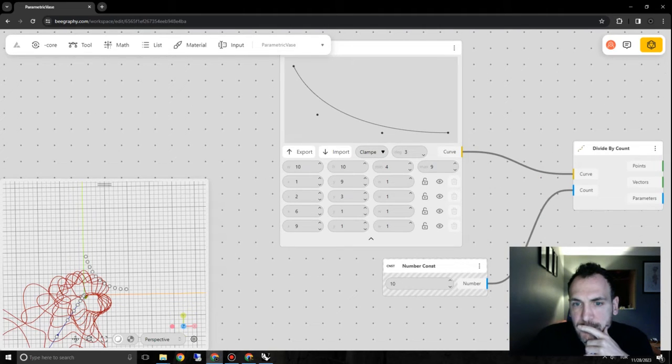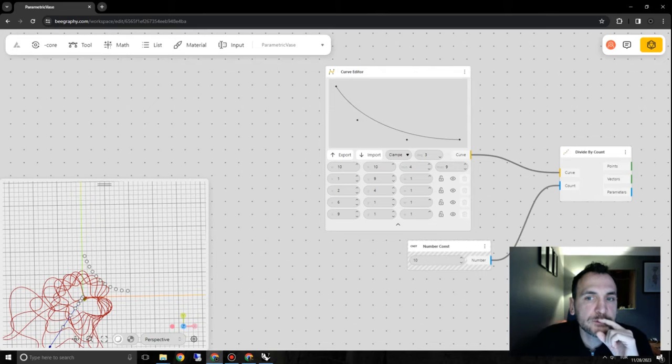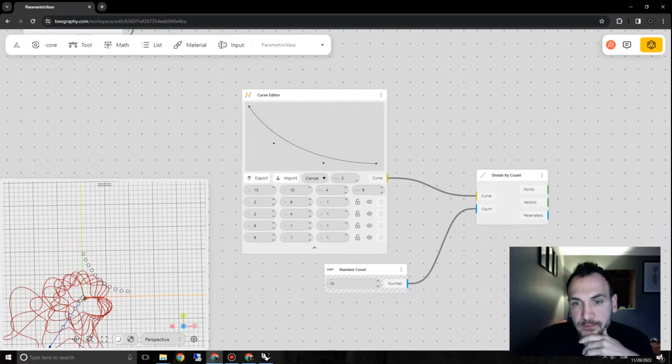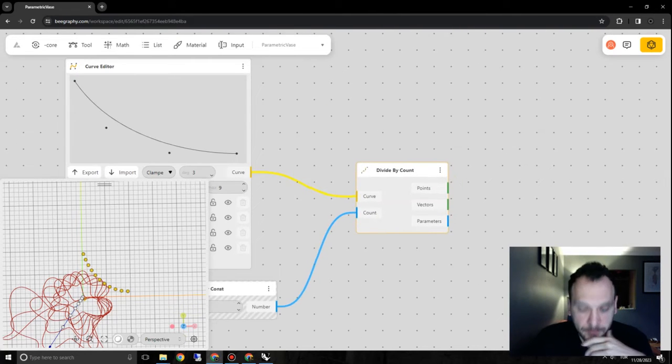Well, we can actually make it, this is, I guess, the number of points. Well, I'm not too comfortable with playing with these because I want to manually change the shape of this curve. But what I want to do is use something like the graph mapper functionality in Grasshopper. So I want to use the values in one direction to be mapped as scalar values. For instance, if this curve is way up, I want that profile to be large, but if it's way down in y value, then I want the radius value to be really small.